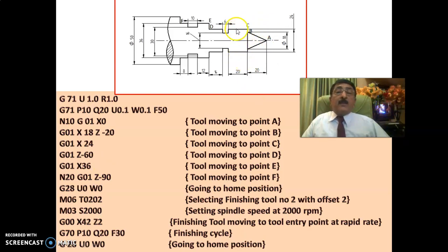That means this is actually not 24, it is 24.2. During finishing with a depth of 0.1, it will remove this, and it becomes exactly 24. This also will not be 20, it will be 19.9, and during finishing it becomes 20. Okay, these things I've already told you.